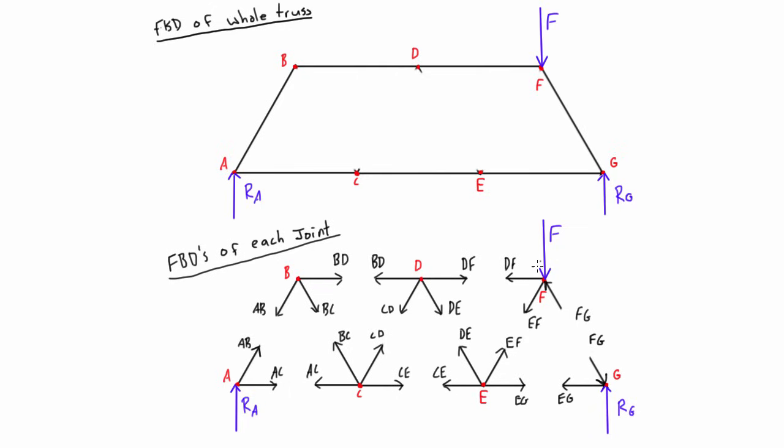So then when we go again here solving this, we have one known and then 2 unknowns. We have enough using sum of forces in x and y, and knowing the angles, which all happen to be 60 degrees, that we can solve for these other 2 unknowns. And then once we do that, if we find some of them to be in compression, we repeat the process, and then we continue on the whole way across the truss, and then eventually we'll be able to solve for all of the forces in all of the members. We also could have started on this end and worked this way, but I think you get the point now.